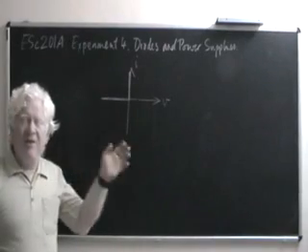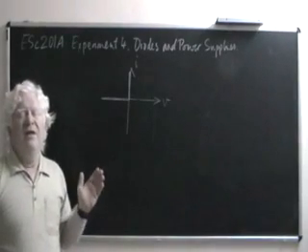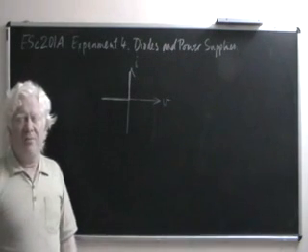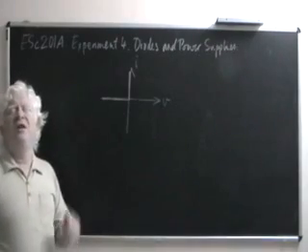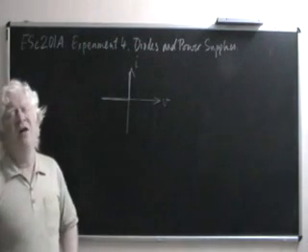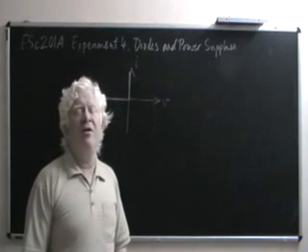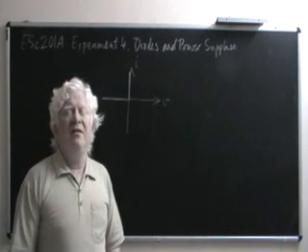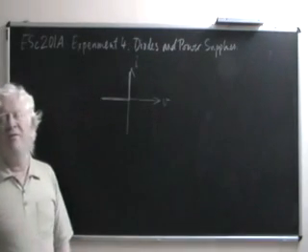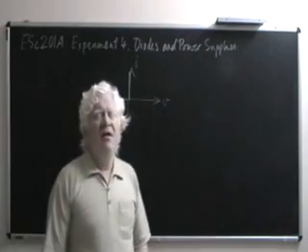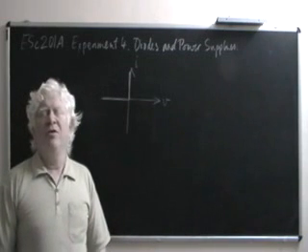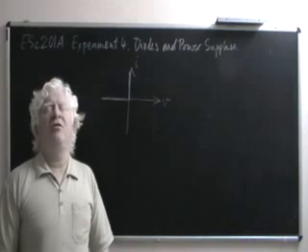No practical diode that's made with electric circuits is ever going to be ideal. But it tries to be ideal in a major part of its characteristic. Superposed on this, I will draw the characteristic of a non-ideal diode, of a practical diode. A practical diode does have a small amount of current even when a reverse bias is applied, even when a reverse voltage is applied. And that in fact flows until a very large reverse voltage is applied, when the diode breaks down and allows a lot of reverse current.